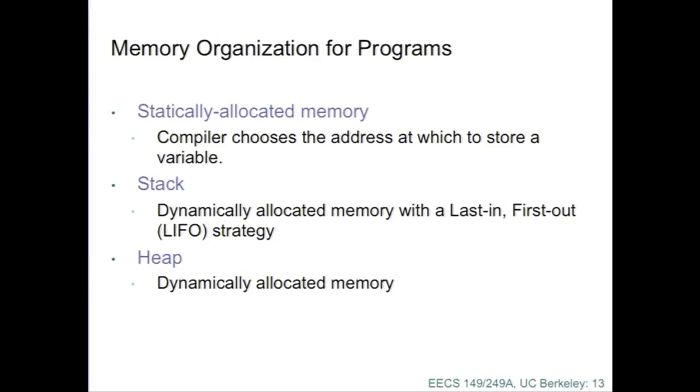The first reason was that flash memory in particular wears out after a certain number of accesses. You can only write to it so many times, and then it breaks down. You can typically only write about 100,000 times. So if you have a 2 gigahertz processor, you could wear out your flash memory in a small fraction of a second. Yes? Oh, yeah. I'm going to talk about that a little later, so hold that question until we get to it.